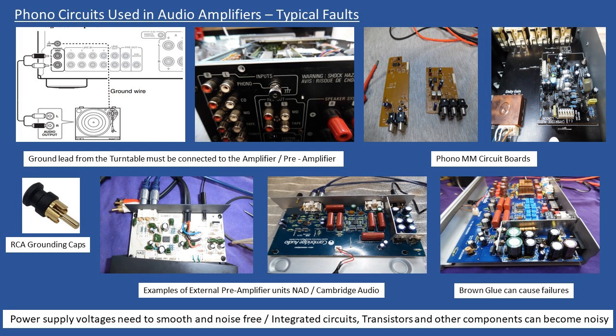And then for your power supplies, if you look at electrolytic capacitors and you have power hum coming into these preamps, you may well see that the electrolytic is slightly raised, or maybe you can see some form of electrolyte leaking out. But check that, make sure that it's not due to a power supply failure. And then the same also with the higher frequency filter capacitors. And then when I refer to the brown glue, very, very common.